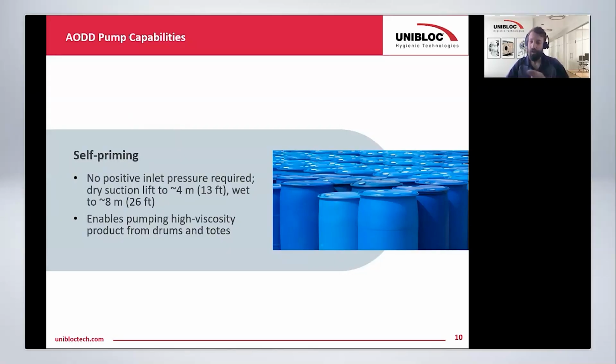And so that's kind of how suction lift works with an AODD. You don't want to be doing all the work walking when a truck and trailer is going to do all the heavy lifting for you. You don't want the suction to be moving your product the majority of your distance. You want to be pushing it the majority of your distance. It's going to work a lot better.